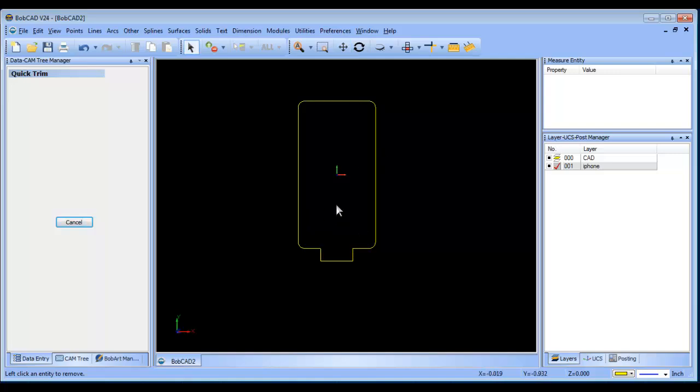Now I want to create some clearance for the phone, because there are buttons on the sides, and again, it's kind of rough estimates when I did the conversion from metric, so I want to just create an offset for this. So we're going to do inside pocket. Now I use layers. A lot of times I don't name the layers, but it helps sort out the different portions of your geometry.